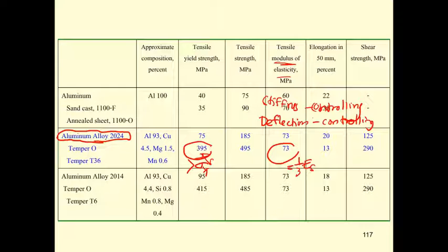You can decide the section passes the maximum moment and the maximum shear, but when you check the deflection of the structure, it gets quite large since it has a low modulus of elasticity.